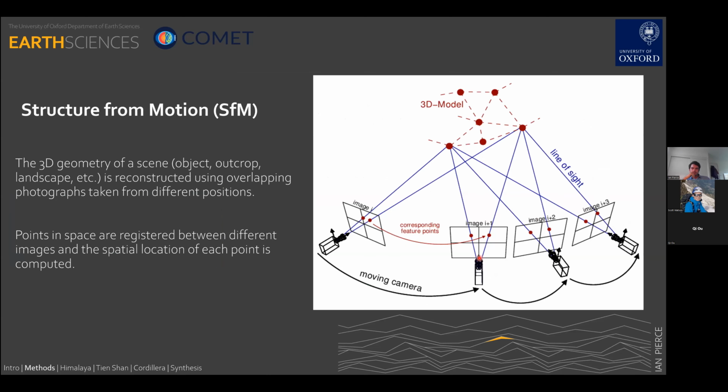Producing similar results as LiDAR, structure from motion uses photogrammetric principles to reconstruct topography using overlapping photographs taken from different locations. I mostly use images from drones or satellites for these reconstructions. Recent technological advances in flight control and positioning have dramatically increased the coverage area we're able to collect with a drone.